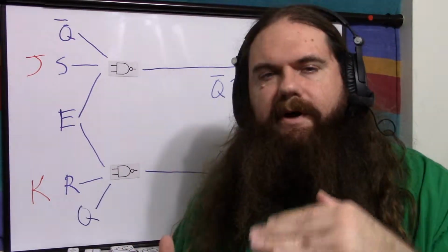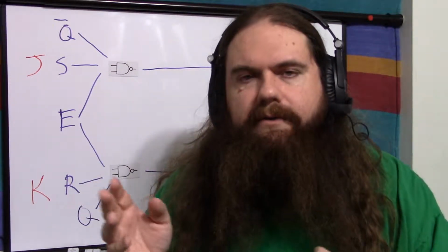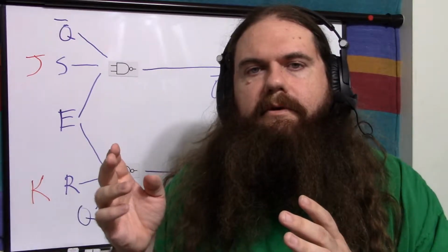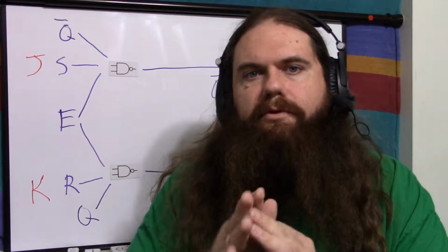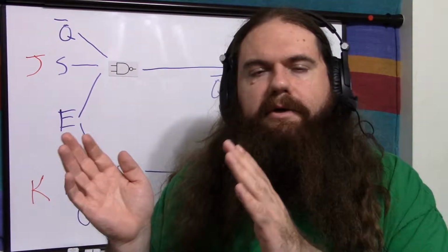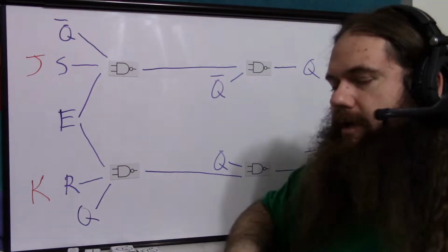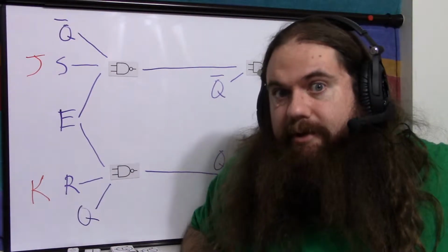It basically modifies the base clock signal, because the base clock signal is going to be your crystal or whatever, and it's going to go high, low, high, low, high, low. And then you edge trigger to create a pulse from that clock signal. So you can create a low pulse or a high pulse, and you can have it be on whichever edge. We'll get into that later. But that's one way to solve it. The other way to solve it is add more transistors.